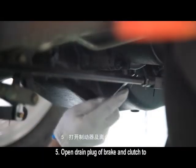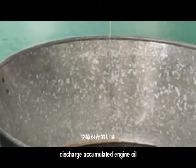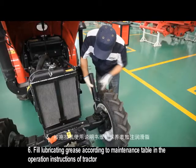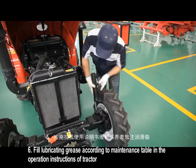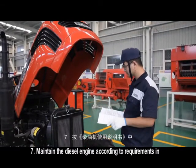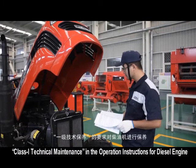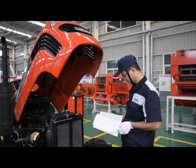5. Open the drain plug of the brake and clutch tube. Discharge accumulated engine oil. 6. Fill lubricating grease according to the maintenance table in the operation instructions of the tractor. 7. Maintain the diesel engine according to requirements in Class I technical maintenance in the operation instructions for the diesel engine.